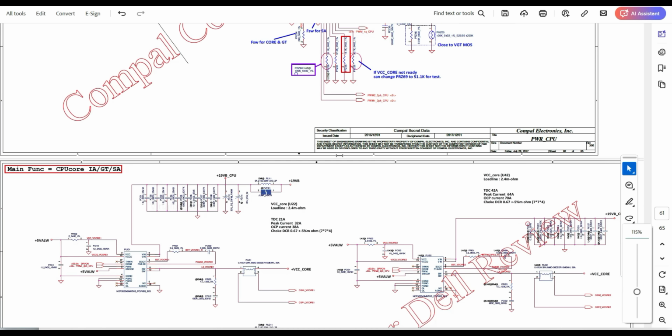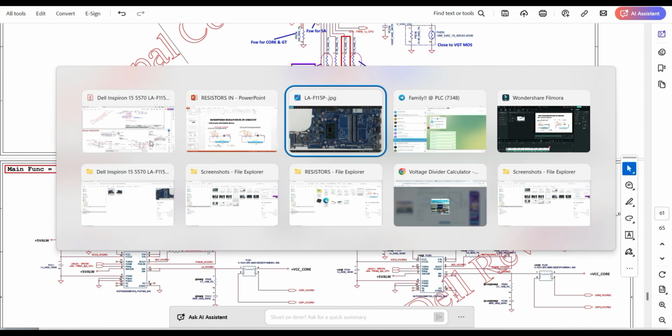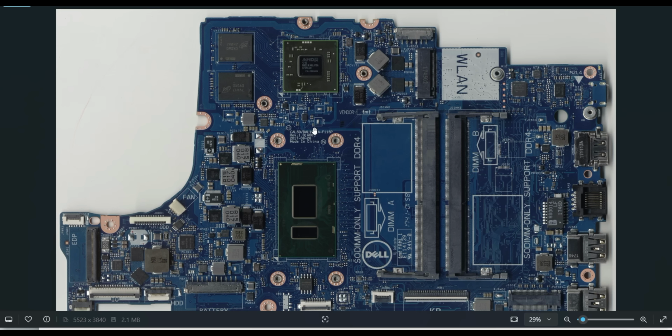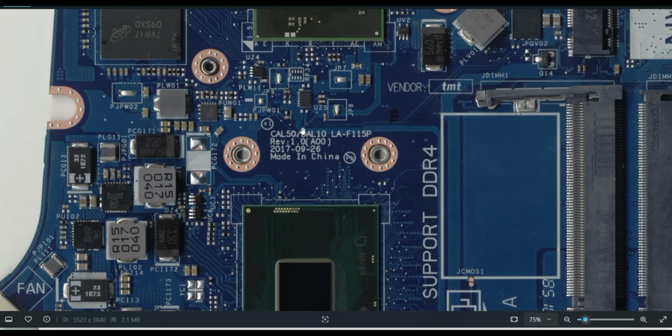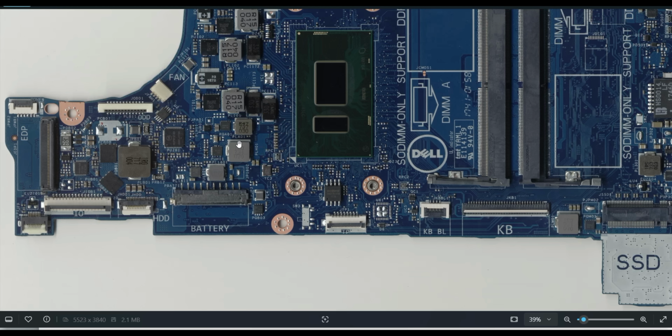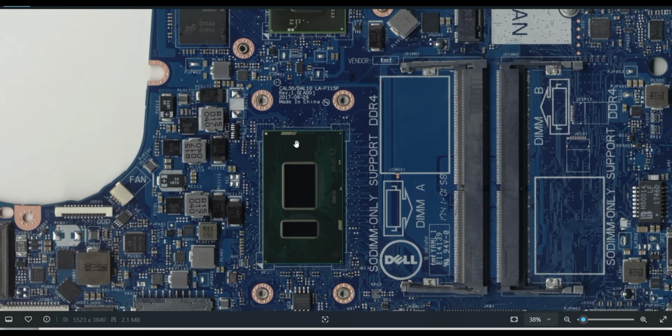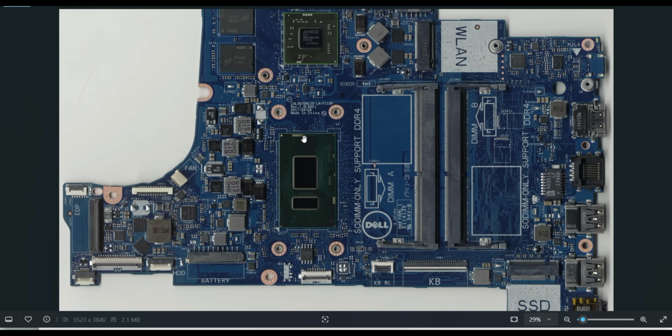Okay, that's it. On this motherboard, we can see the resistors are connected in pull up, or pull down, or series, or voltage divider. Got my point? In any motherboard, these are the four conditions of the resistors. That's it, guys. In any motherboard you take, only the four conditions. Once again I am repeating: pull up, pull down, voltage divider, or series. And for a voltage divider with a thermistor, it depends on the temperature.